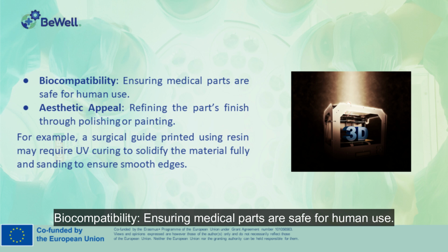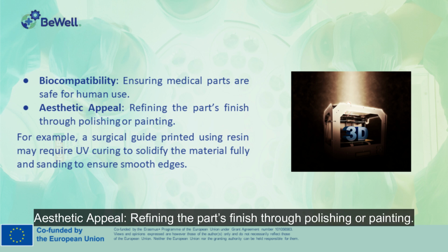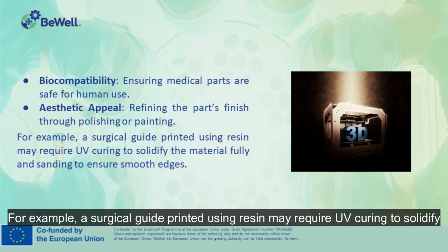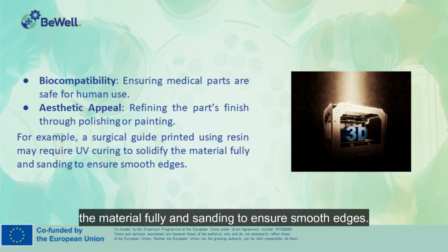Biocompatibility, ensuring medical parts are safe for human use. Aesthetic appeal, refining the part's finish through polishing or painting. For example, a surgical guide printed using resin may require UV curing to solidify the material fully and sanding to ensure smooth edges.